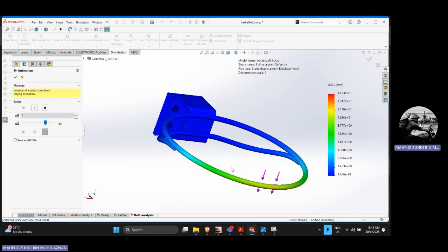And as for the next one, we can add a support bracket, which is a diagonal bracing from the rim to the board, maybe around here, which can reduce the effective cantilever length and lower the stress.